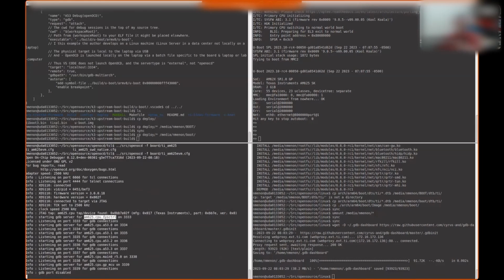You need a special key that TI provides to give access to this. The reason for that is that the security controller has access to a lot of TI secrets, which we wouldn't want people to look at because we have all the firewall protection preventing access, and you don't want to get through JTAG to see it. Fortunately for us, I'm using a GP device right now, so we can actually get inside it if we choose to.